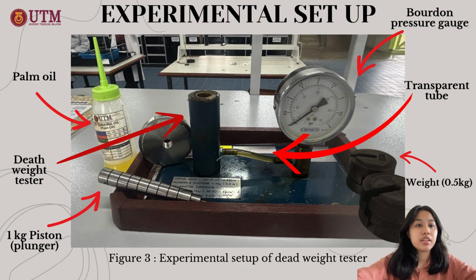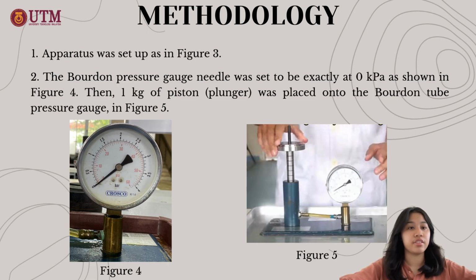So for the experimental setup, number 1 we have the Bourdon pressure gauge, number 2 transparent tube, number 3 weight which is 0.5 kg, number 4 pump oil, number 5 dead weight tester, and number 6 1 kg piston. For methodology, the first step is the apparatus was set up as in figure 3. Next, the Bourdon pressure gauge needle was set to be exactly at 0 kPa as shown in figure 4.